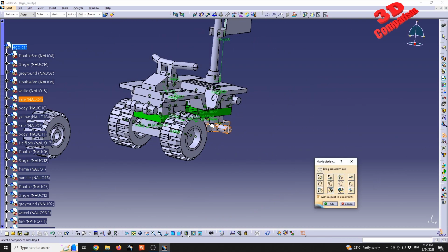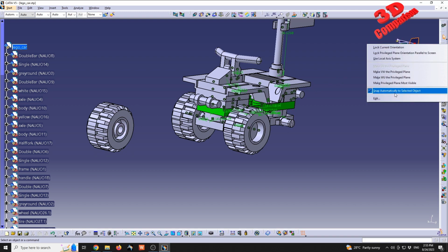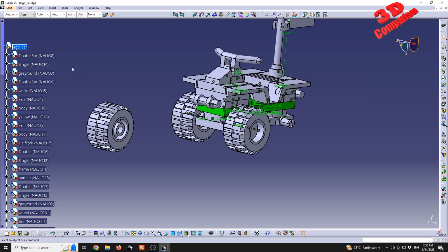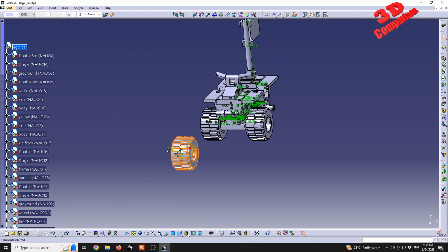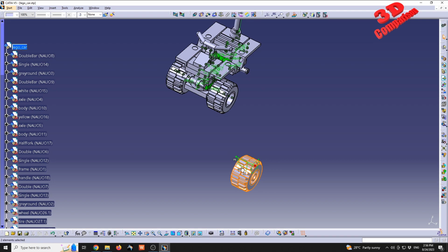And at the end, it's important again to test if our component will rotate on the y-axis, and that both the wheel and the tire rotate. So I'm gonna do the same for these two. Since I already have the compass set to snap to selected by right-clicking and have this checked, I can also do a rectangle selection to get both of those at the same time, move them to position, and afterwards we're just gonna slightly help the software by rotating this.